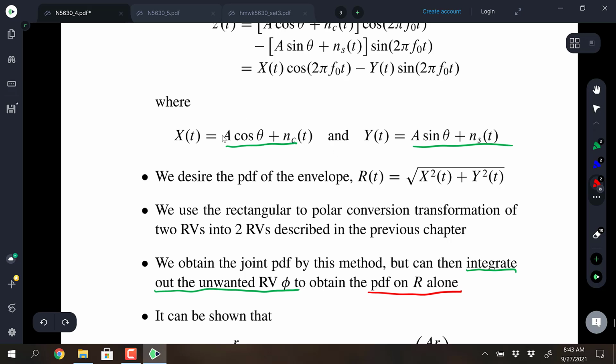It'd be like if we were modeling the impact of a channel, we would just have NC and NS if it was purely diffuse and assumed to be Rayleigh at that point. And the reason why it's said to be Rayleigh is because the envelope of two Gaussians that are uncorrelated at that sample time will be Rayleigh in envelope.